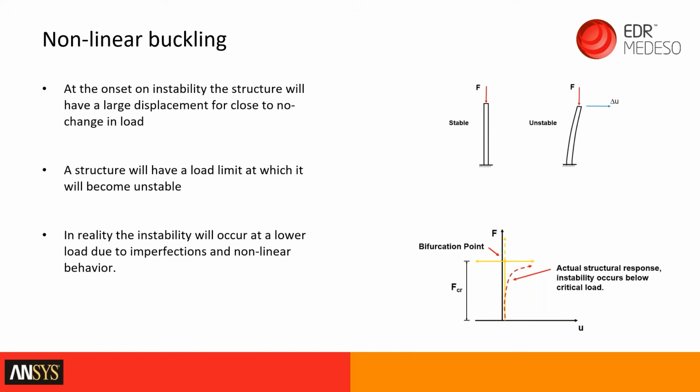So normally it gives you a perfect buckling load. In the real world, things like non-perfect geometry, corrosion, any imperfections perturb the model, and it means that the actual collapse load comes on a little bit earlier. So if you're doing buckling analysis, you need to keep in mind it's non-conservative results that you get, and you need to apply some sort of safety factor.